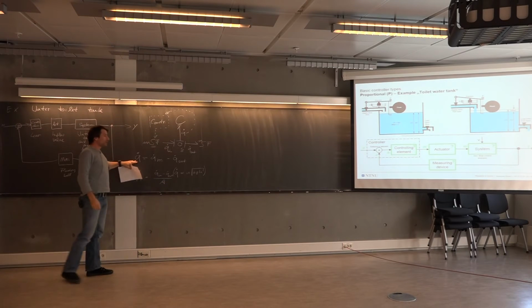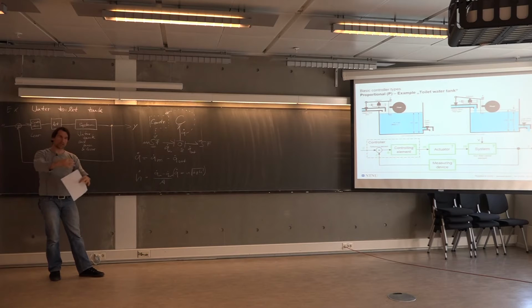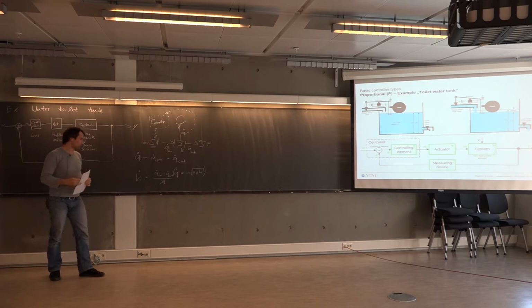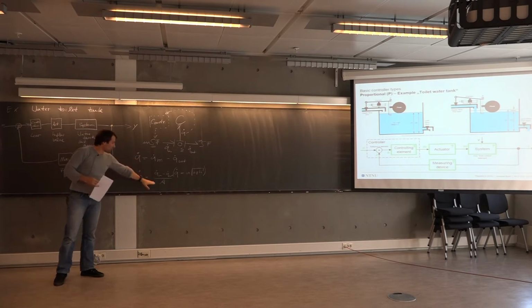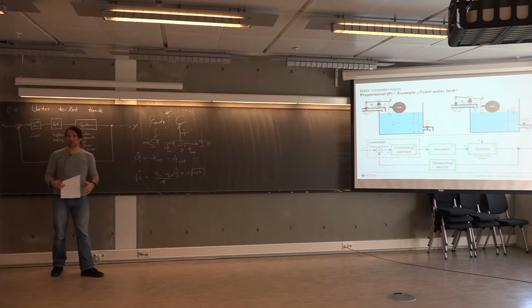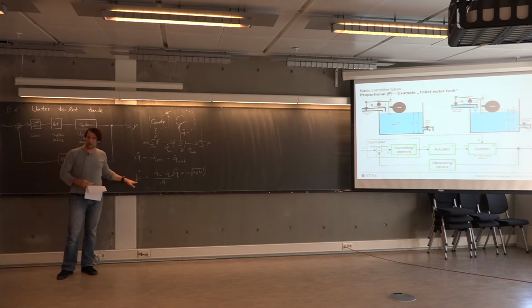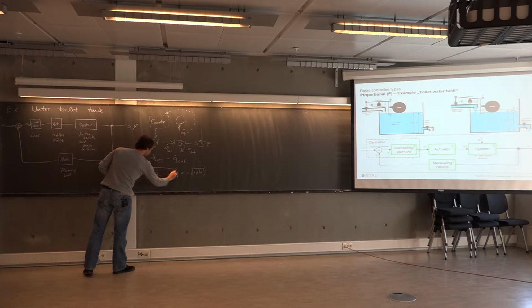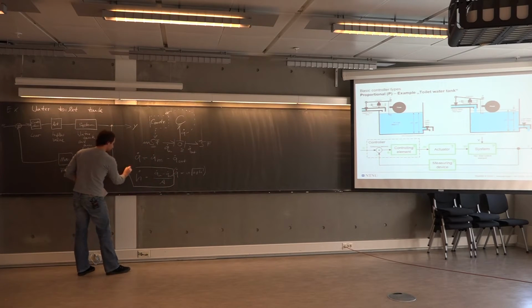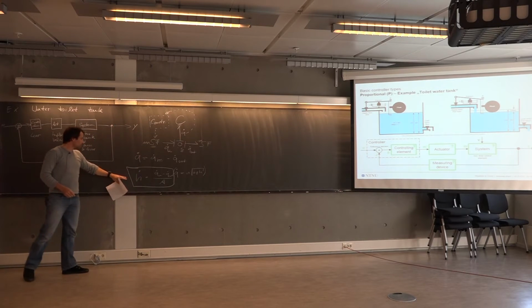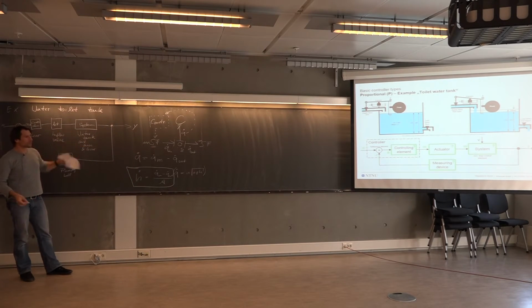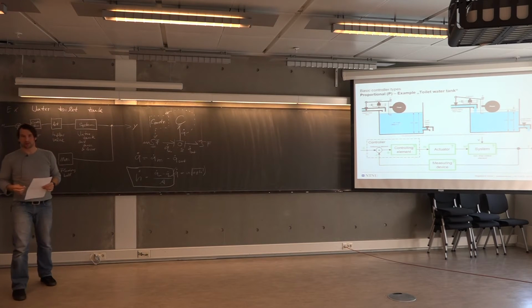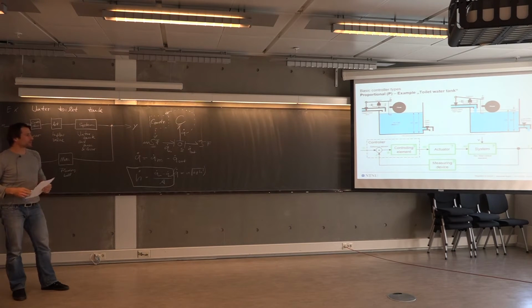If we divide the flow rate, which represents the change of volume in the tank or in the reservoir, by A, the cross-sectional area, we basically get the change of water height in that reservoir. And this is the equation which basically represents our system in a very simplified manner, but sufficient enough to deal with that from a control perspective.